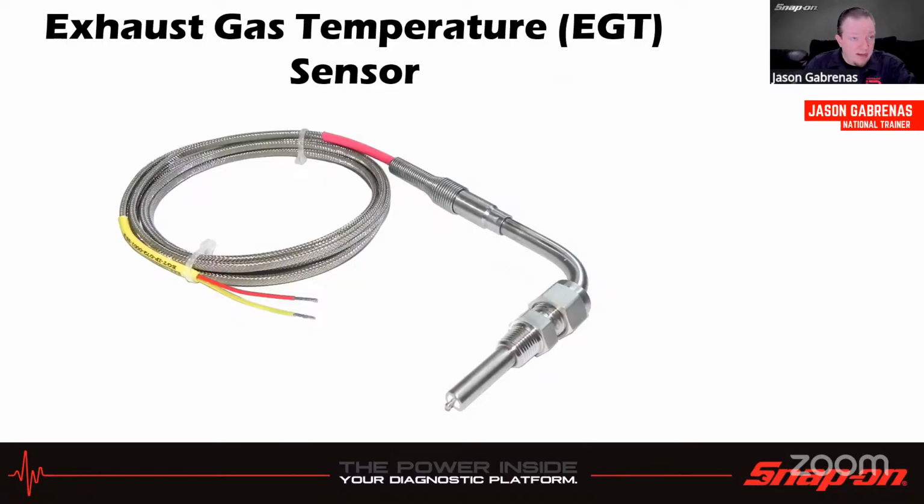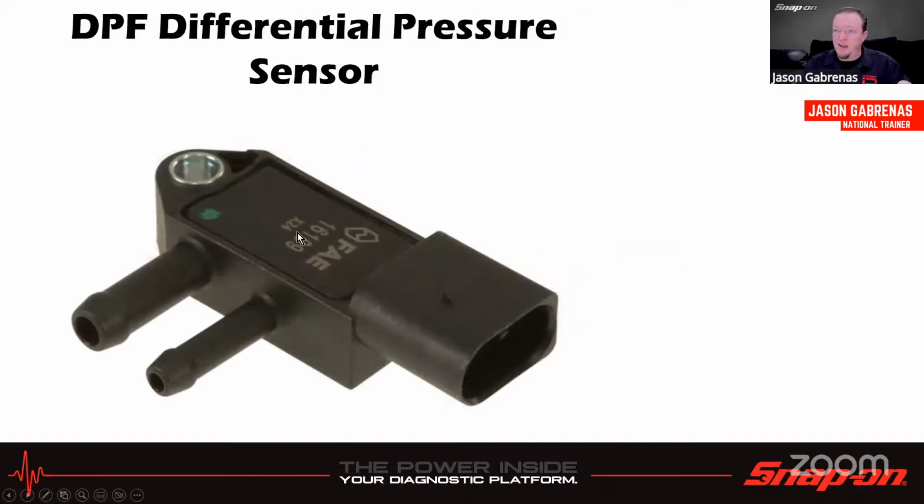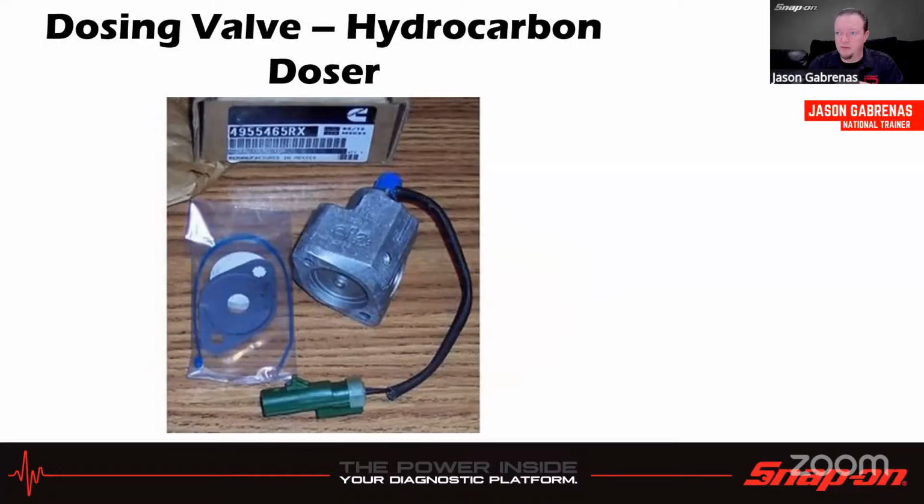Also along the way, as I showed in the diagram earlier, we got the multiple EGT sensors along the way. We also have the DPF differential pressure sensor. So this measures the pressure going into the DPF and the pressure going out of the DPF. So the computer can calculate how much it's clogged, if it's clogged, and whether or not it's actually working and whether or not the flow is working.